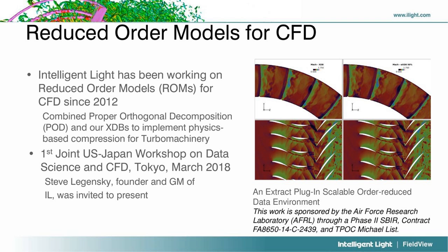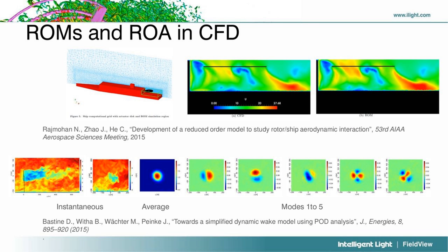So why is that interesting for CFD practitioners? What are the benefits of modal analysis in general? You can see a few applications here on this slide, but basically it comes down to what you can do with this approach. Reduced order models allow you to build, well, as the name says, reduced models. And so if you have complex flows, if you have very long unsteady simulations, you can obtain something that is smaller, that is lighter to use, a model, and you can use that for further simulations or further computations.